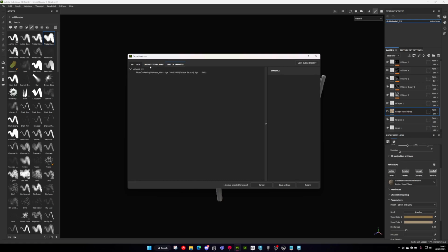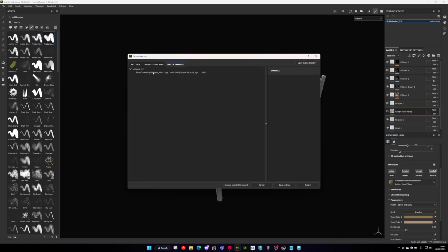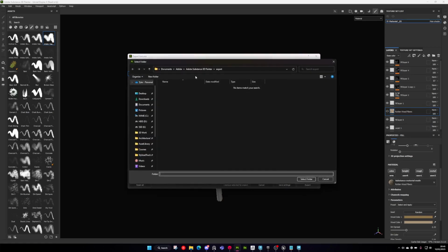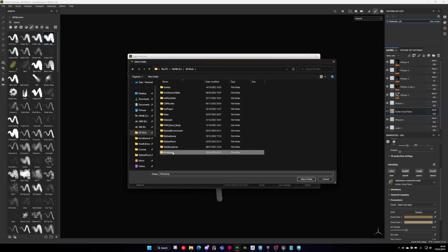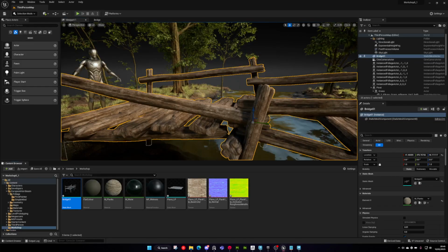Generally, in production, you can have this mask be quite low res because you can use this mask to blend between your regular texture and a tileable texture. So then you can get some of that quality back, because otherwise each mesh having a 2K secondary texture can become quite expensive. Even just making it a 1K texture is 4 times less the size. So let's just export that and bring it into Unreal.